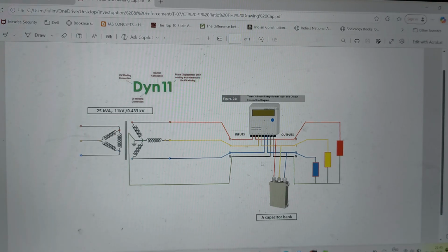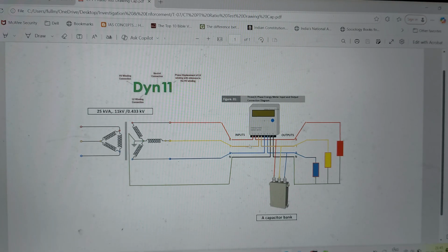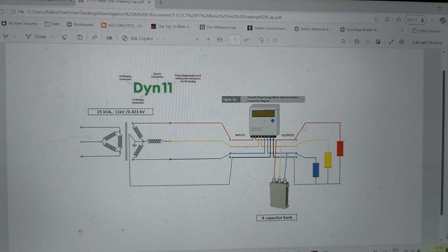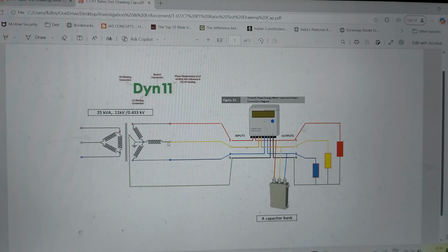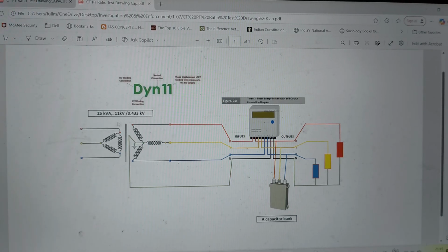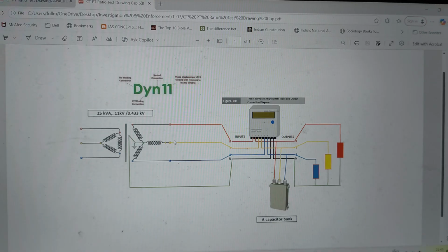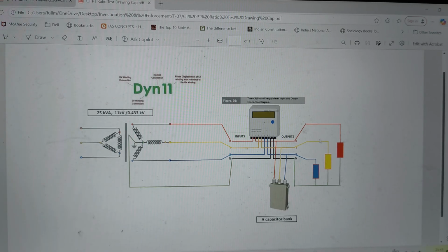And this capacitor bank is actually to stabilize or regulate the voltage, because every time you have an inductive load, every time you run your welding machine or your water pumping motor, it is going to draw a lot of current from the transformer, and whenever current is high in the line, the voltage will drop so as to balance this kVA. That is a different topic altogether, but just as general information, any high current will dip the voltage, and if this welding machine is operating the whole day, then the voltage fluctuation will also be there the whole day.